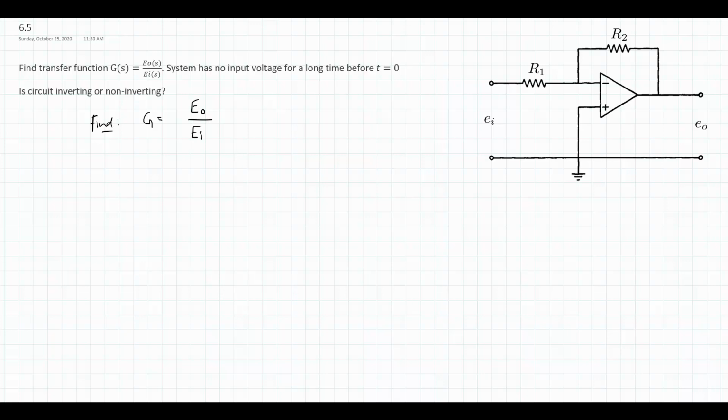With an op-amp circuit, I'm going to choose not to use the voltage loops or the Kirchhoff laws, but I think it's going to typically be easier to use the nodal voltages, or finding the voltage drop between neighboring nodes, to develop equations that way. So for my diagram, I'm going to make my own version of this circuit that I can mark up easier. I have this node connected to ground.